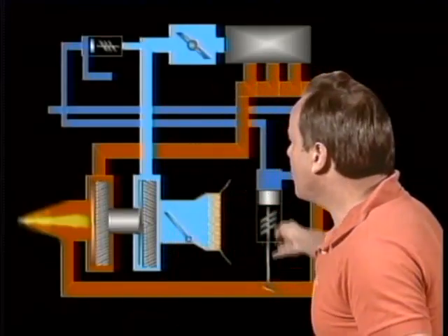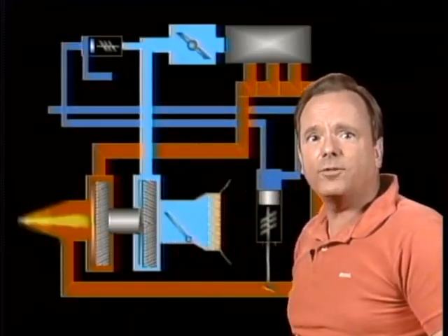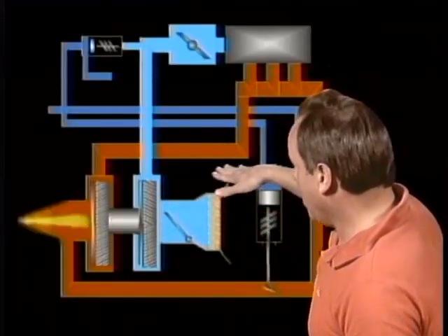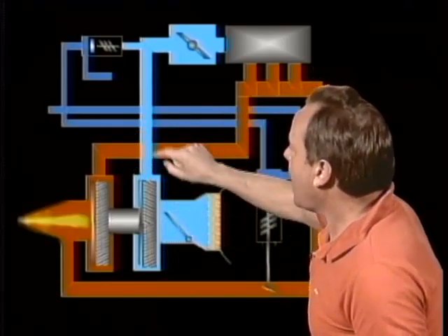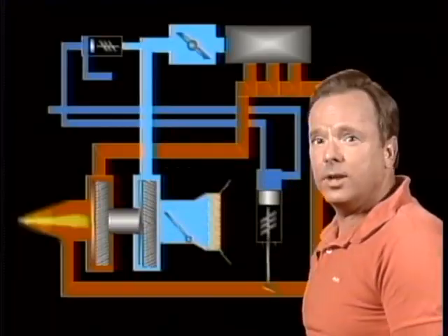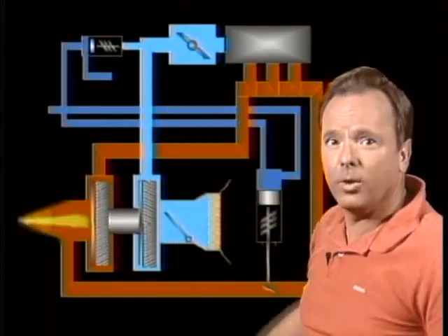So they're going to ask you on the test, what is the purpose of a pressure ratio controller in a turbocharger system? And it's to control the position of the wastegate, and that's the wastegate right here, after the aircraft has reached its critical altitude. And the reason for that is the turbocharger will start working real hard when the airplane has reached its critical altitude. Ambient air pressure drops off, and it's much, much less. And the pressure ratio controller limits how much ratio of boost. We'll say a 2 to 1 boost is all it will allow over ambient, and it limits that so that you're not overheating the turbocharger and having too hot air going into the engine.